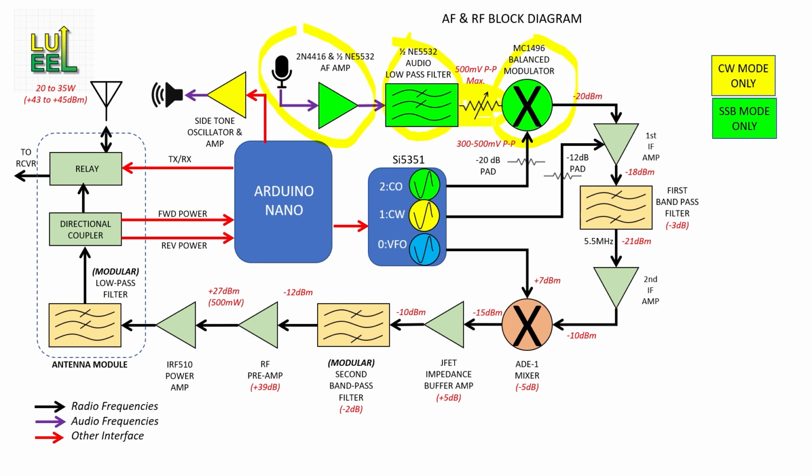If I set this pot too low, then my output power suffered. But if I set it too high, then I drove the RF stages into saturation and distortion. And if I moved toward and away from the mic while speaking, I could create both issues. So I really need some form of AGC in here.